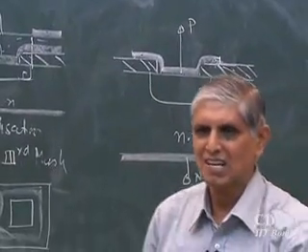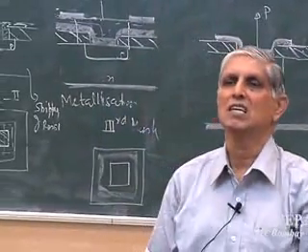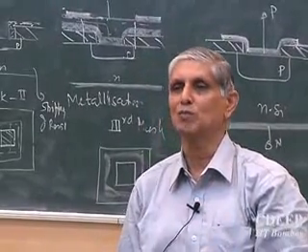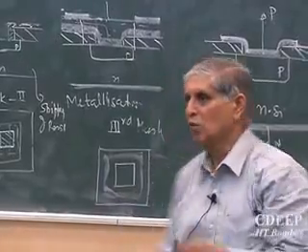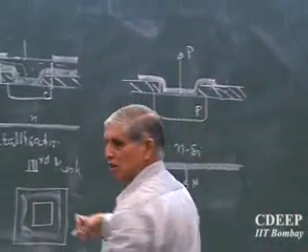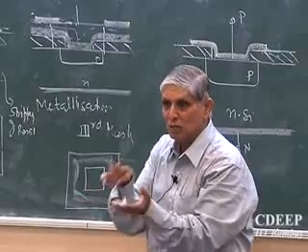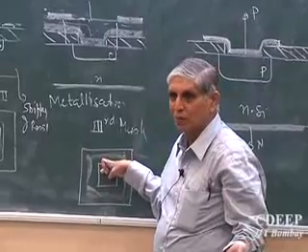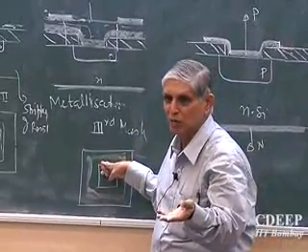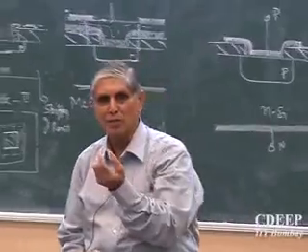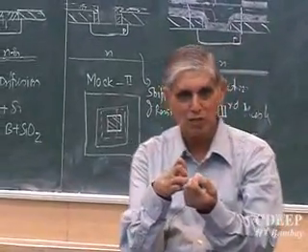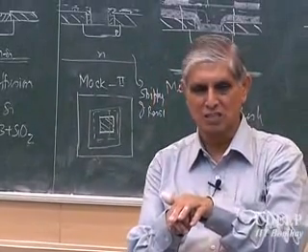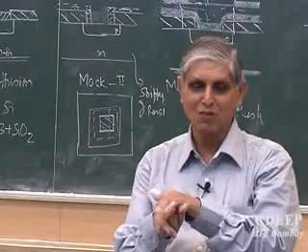Three masks. As I said, to make integrated circuits in CMOS, you require around 24, as many as 30 sometimes, or Intel's process is 27. Now what is the problem with a larger number of masks? You have just seen for 3. I have to keep aligning all of them. Now these features are big enough for a diode, but in the normal case technology is now 22 nanometers. So for smaller dimensions, the gap between these is very small. The alignment has to be very perfect, otherwise half the chips will not work. So that's why aligners are a very important process.